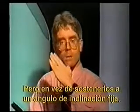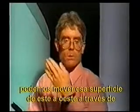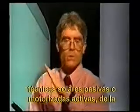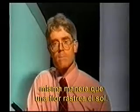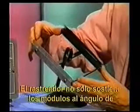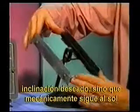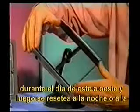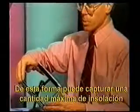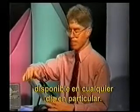But instead of holding the modules at a rigid fixed tilt angle, now we either through passive solar techniques or active motorized techniques can move that surface east to west, just like a flower would track the sun. This model of a tracking device helps to illustrate what I'm talking about. Not only does the tracker hold modules at a desired tilt angle, but it would actually mechanically follow the sun during the day, east to west, and then reset itself either in the evening or the next morning so that it can catch the morning sun. In this way, it can capture a maximum amount of insolation that might be available on any particular day.